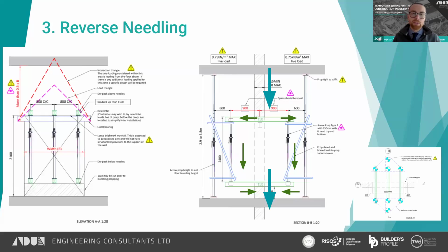So the propping from the floor to the ceiling here is used so that there's something to brace back to for lateral stability. A tall prop such as this is not required on every prop, it's just on a few, so that the props can be braced back, and we've got something to build from as well. It helps with the constructability. If you've got very tall ceilings, then propping like shown becomes quite difficult, so we can use scaffold rakers or something like that. It's essentially just to provide some support.